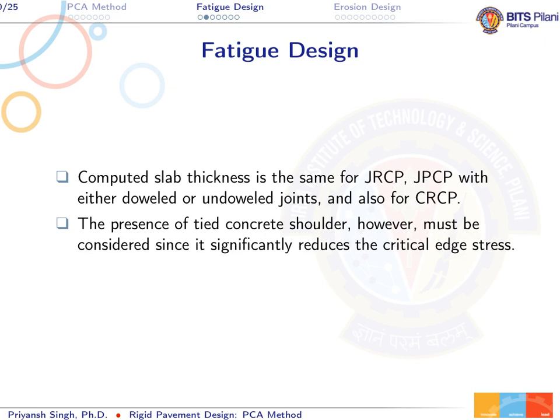However, if the concrete slab is tied with the existing shoulders, that case must be considered during the design process. Because if the pavement slab is tied with the shoulders, then the critical stresses on the edge will reduce significantly, and you need to take care of this reduction during the fatigue design.